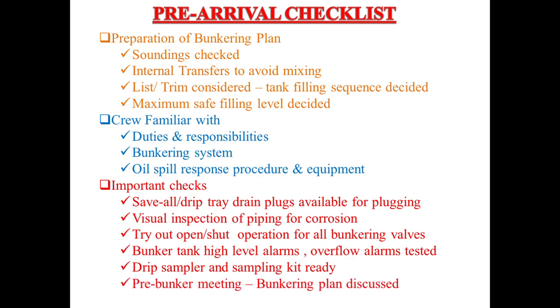Then we have the pre-bunker meeting, where the bunkering plan is discussed. After the preparation of the bunkering plan, we discuss in which sequence we are going to take, how much we are supposed to fill, where the person has to be, and so on.